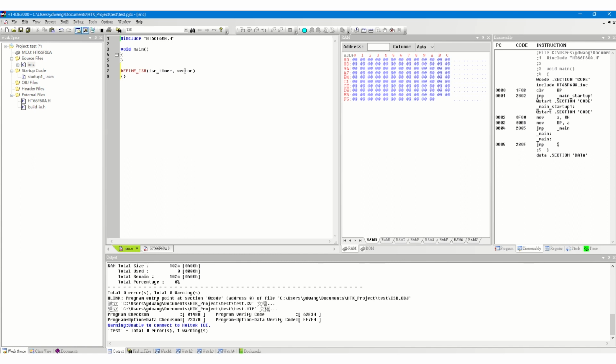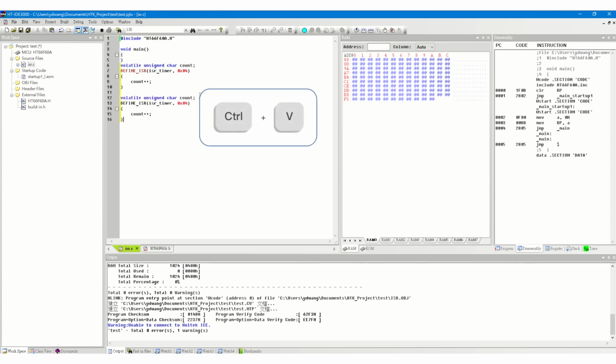The entry address is generally a multiple of 4. The specific address can be obtained from the datasheet. Define global variables for interrupts, if used, using a volatile qualifier. If users want to define more than one interrupt entry, modify the interrupt name and entry in the same way.